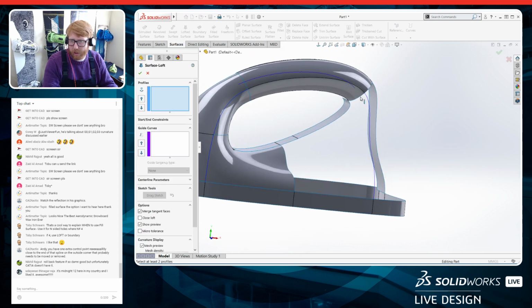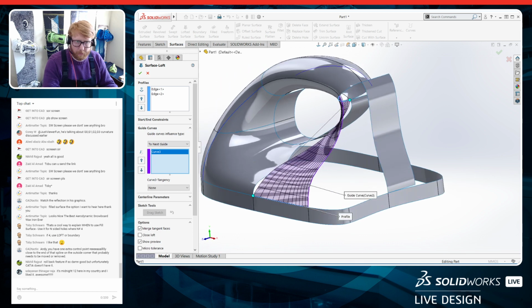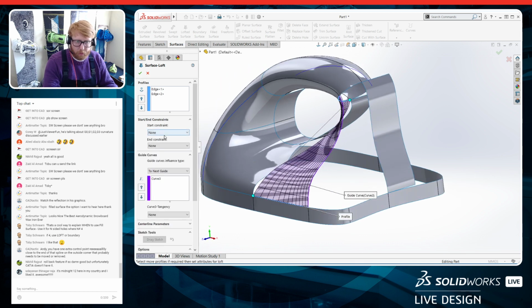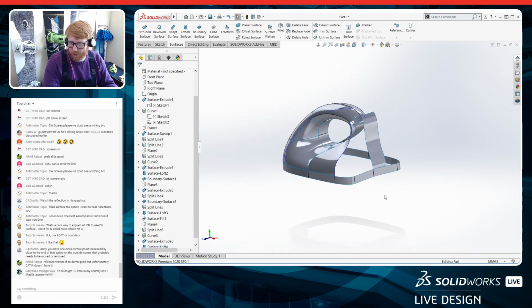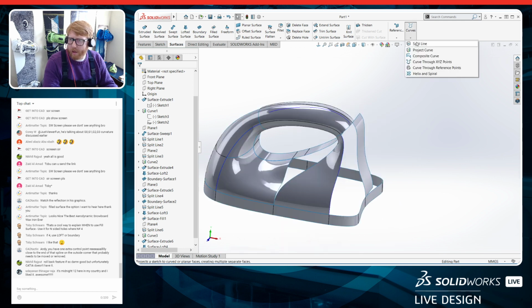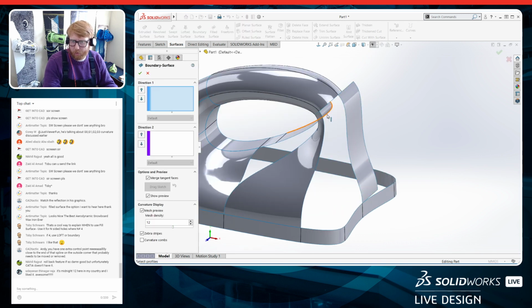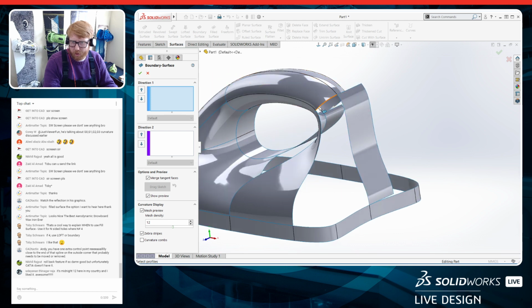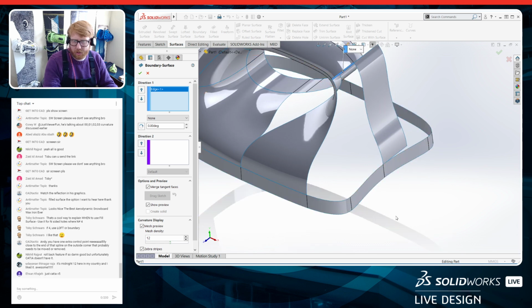And we'll do a lofted surface from here to here. And we'll select that curve and we'll say tangency to face, tangency to face, click OK. And now we'll turn off that curve and I'll put in my boundary surface right here. So I'll go from the top here, I'll get this quarter of my ellipse. And then down here, you'll notice this is actually two edges, right? So I need it to act as though it's one edge.